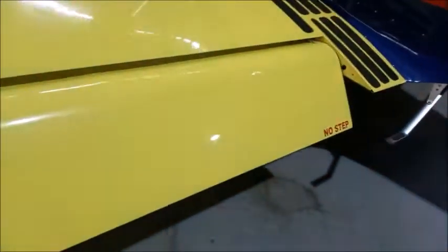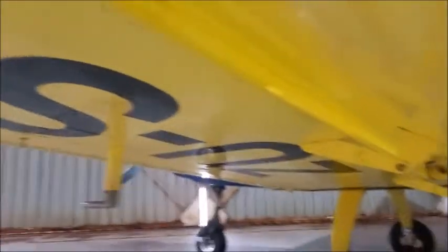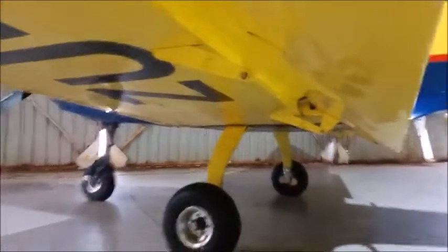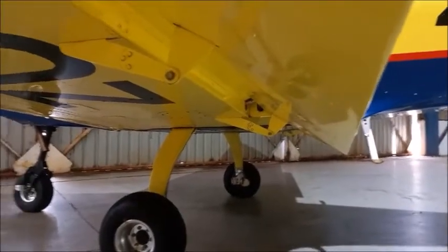The paint markings help us to see that nothing has been moving. We also have to come in there, have a look at the bottom and make sure that all the nuts and bolts are in place for the flaps, so that we don't lose them. Okay, so we can see that all over there.